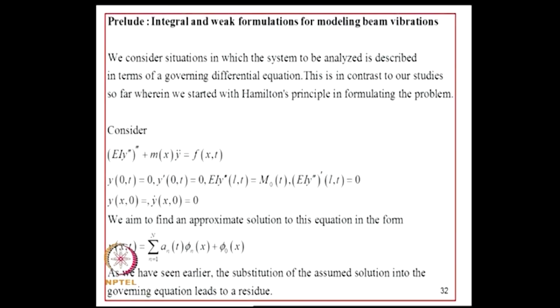Now as a prelude to developing a finite element model starting from a partial differential equation, we will revisit some basic notions about how to do this by considering a simpler problem. So what we do is we consider situations in which the system to be analyzed is described in terms of a governing differential equation. This is in contrast to our studies so far, wherein we started with Hamilton's principle in formulating the problem.